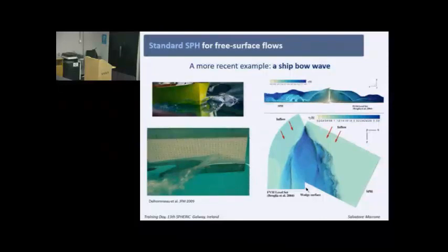This is the view from the top. You can see how the SPH can describe better and more finely the evolution of this plunging wave. And you can see also the different scars that the wave produces inside the flow. These correspond to underlying vertical structures that are generated due to the splashing of this wave. And this was done with the standard SPH. So we were quite happy.